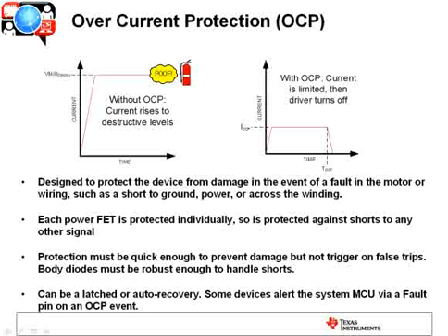So typically the motor drivers have the on-chip overcurrent protection built in. They are monitoring each individual FET, so you're fully protected against these shorts. When an overcurrent event occurs, the fault can either be latched or auto recovery. So if it's latched, the device is going to tri-state, it's going to shut down, and the system controller is going to have to come in and reset it. If it's auto recovery, it'll wait a preset amount of time and it'll try and resume operation.